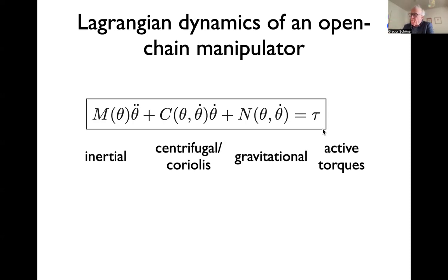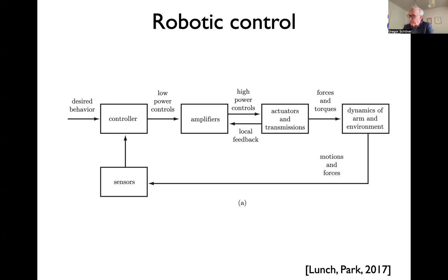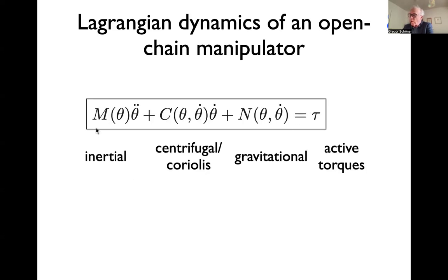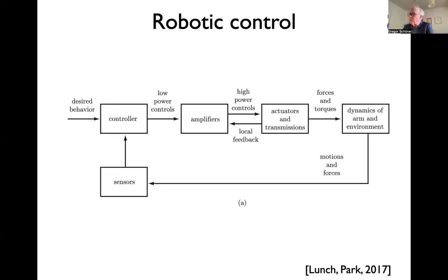And then the control problem is to possibly adjust the torque that you send there as you're sensing that your arm isn't doing exactly the right thing, which could be due to the fact that you made a mistake in computing this torque, or that you're not estimating this right. There are some parameters that are not right, or there's some physical interaction with the world that changes the equation in ways you don't know. And that's what you have to react to.